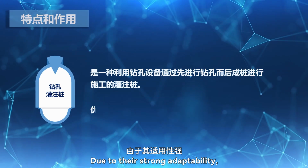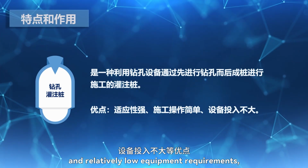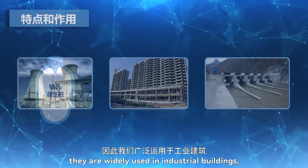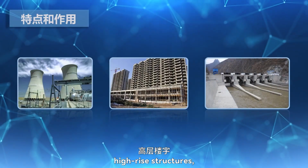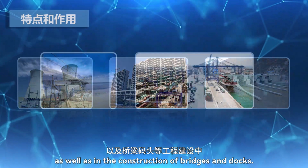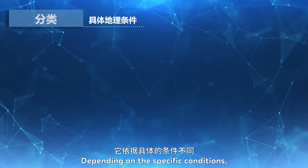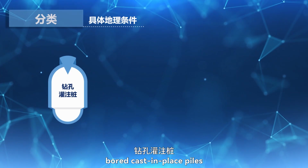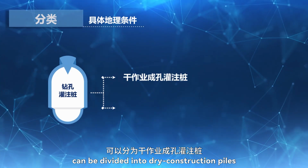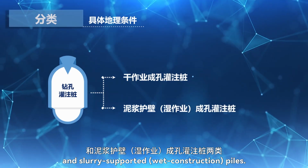Due to their strong adaptability, simple construction operation, and relatively low equipment requirements, they are widely used in industrial buildings, high-rise structures, hydraulic and hydropower projects, as well as in the construction of bridges and docks. Depending on the specific conditions, bored cast-in-place piles can be divided into dry construction piles and slurry-supported wet construction piles.